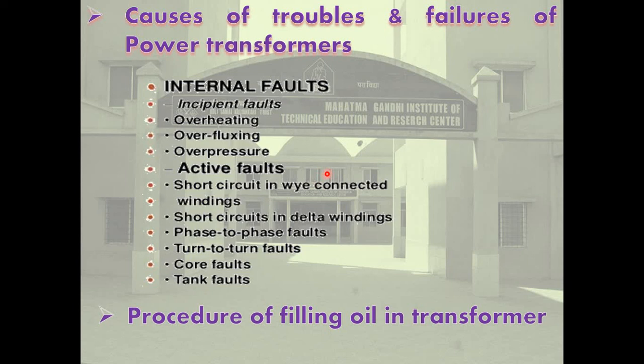Now, internal short circuit. Internal short circuit occurs due to sustained overload and insulation failure, fault in tap changer, failure of end turns of coil due to overvoltage surges, bad solder joint causing local overheating and open circuit, and aging of insulation. Internal short circuit remedies are overcurrent protection, earth fault protection, and differential protections.